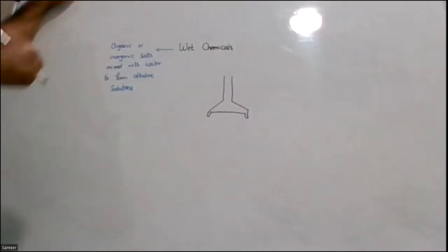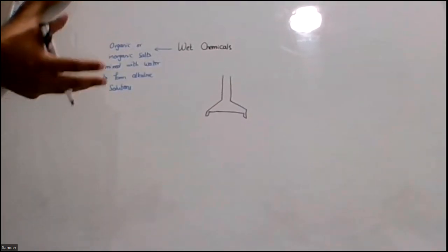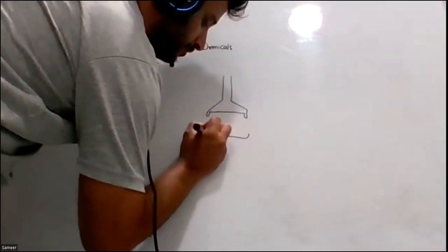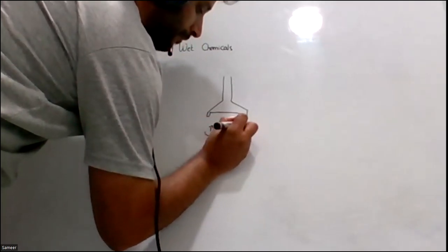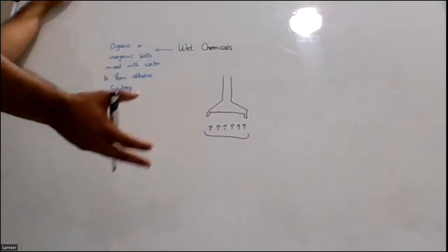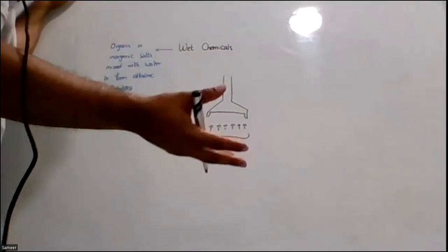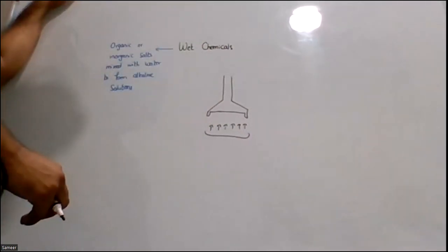A canopy hood is the hood that has lower edges. Why does it have lower edges? It's because it wants to extract the maximum amount of heat and smoke from the cooking oils that are being burned. The purpose of the hood is to extract all the heat, smoke, creosotes, anything released from the vegetable oils or animal oils, fats, through the ducting system to the outside of the facility.